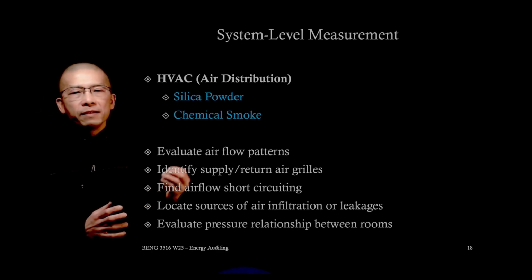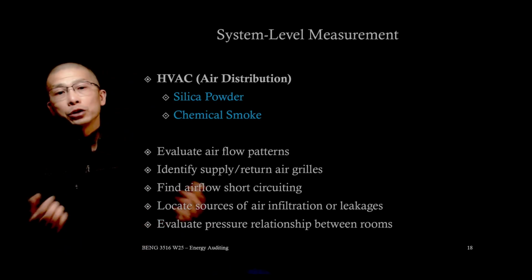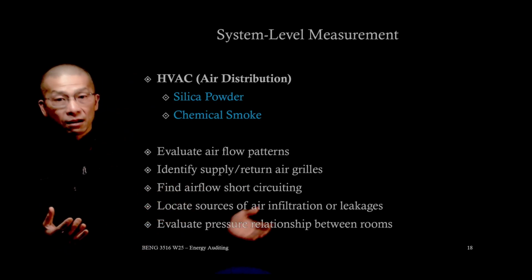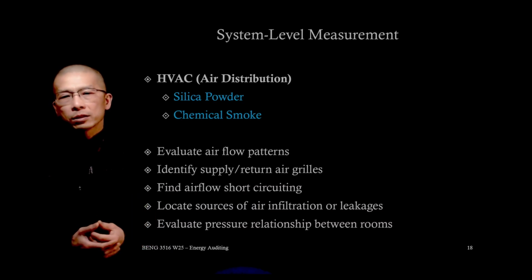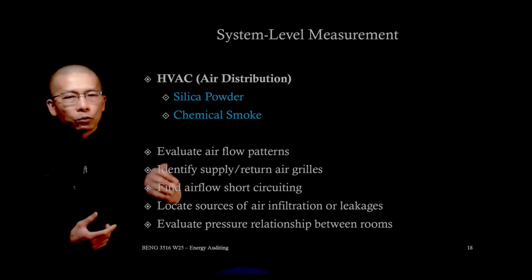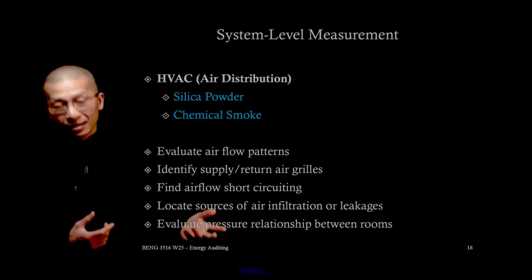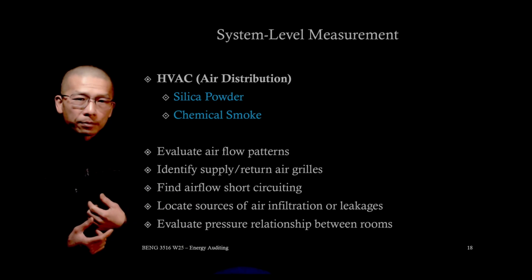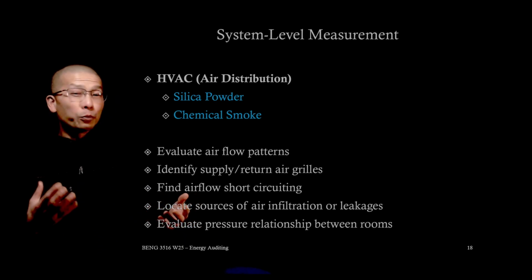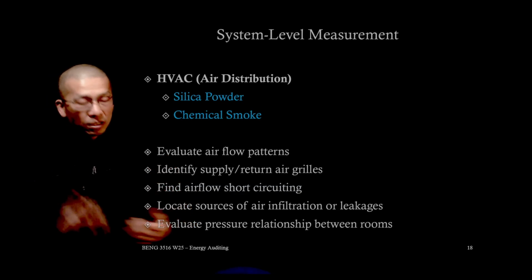Finally, by observing smoke movement between adjacent rooms, we can evaluate pressure relationships. For example, airflow consistently moving from one room to another indicates a pressure difference that may be intentional, such as for isolation or washroom spaces, or sometimes unintentional, right? Then that will contribute to comfort and air quality issues.